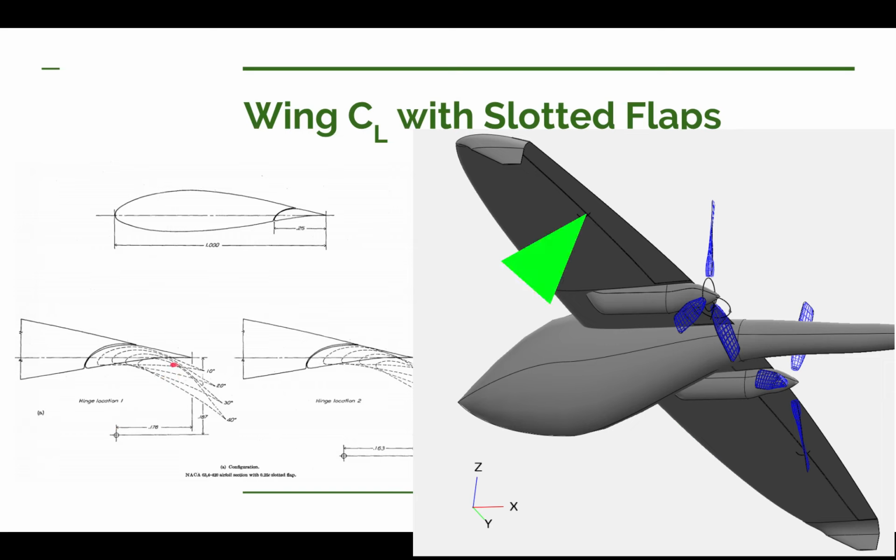So that leaves some mid-span hinges and a hinge out at the wingtip if we're going with full-span slotted flaps. Well, what we can do, at least out at the wingtip, is let's take advantage of having drooped tips. Tips that droop down far enough that we can attach a hinge to. Also has the advantage of having that drooped tip be dual purpose. It can be a hinge, plus it can be like a winglet, which will increase our effective aspect ratio, which of course helps with the efficiency of our wing. So then the only drawback then is mid-span.